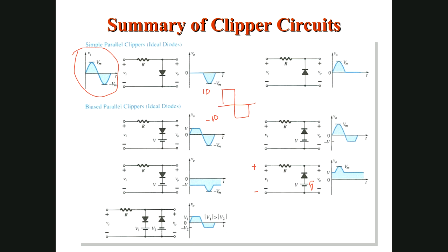Now if you can see, this is the N side of your diode, this is the P side. So your input value of 10 volt is making your diode reverse bias because this input is positive and this is N, and this battery is making forward bias because P is getting positive. Now which one is big? Your input is 10, so it is big. It means your diode is reverse biased.